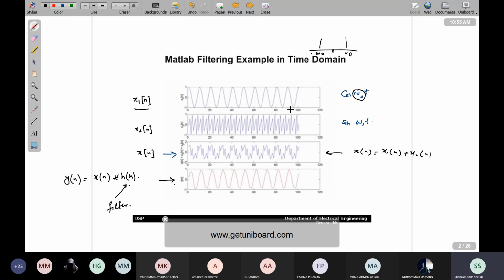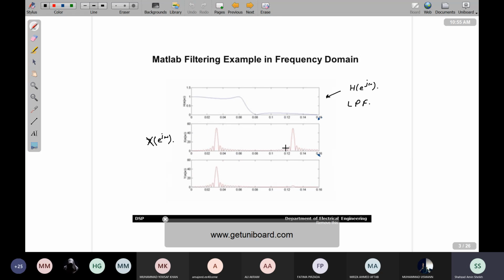So in दोनों signal को जब हमने superimpose किया, we have got this, and now this one is the frequency response of this composite signal, where we are watching clearly two frequencies. One is this one, the lower frequency component, and the upper frequency component, and we are showing it from 0 to pi. So there will be the replica of this on the minus pi side as well. The lower frequency component and the higher frequency component, the replica is coming from the definition of this thing.